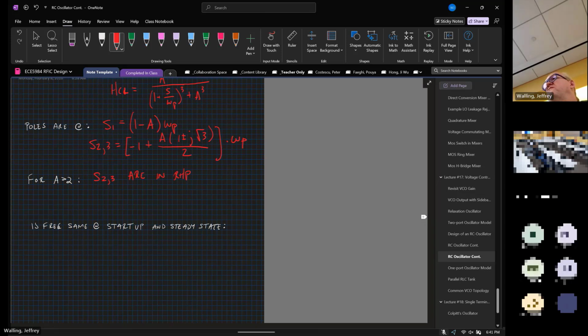It's unstable, right? So it'll cause exponential growth. That exponential growth will self-quench at some point, and move the poles from the right half plane to where they land exactly on the imaginary axis. So our system starts off with our poles right here, and then as the oscillation builds, the wave will start to saturate. It'll lose some gain because of that saturation effect, and these poles will move to where they land exactly on the imaginary axis, and that is where we sustain oscillation.